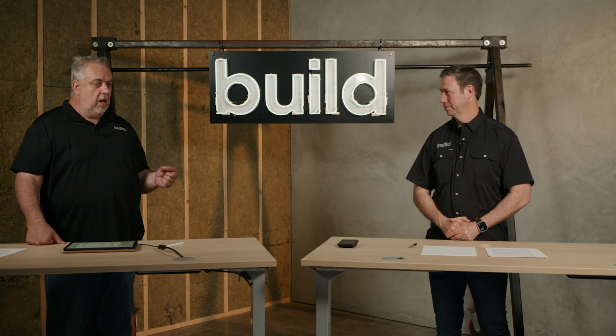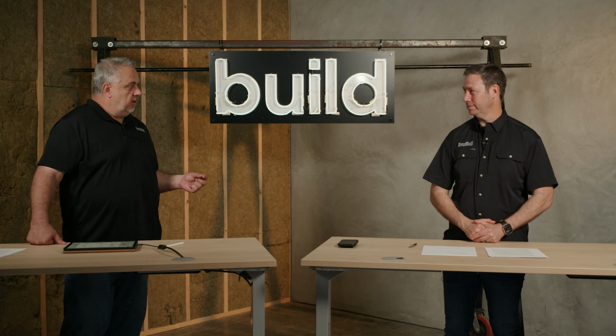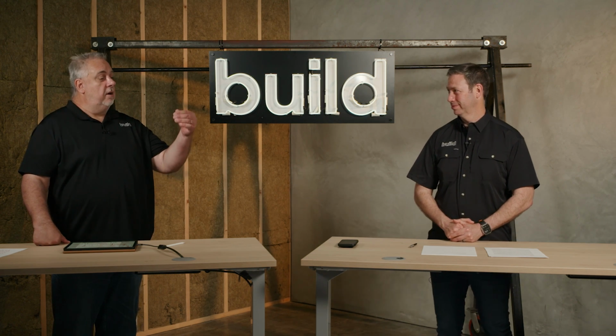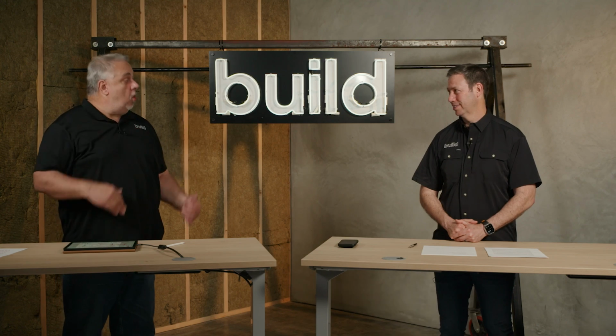When the homeowner called a friend of mine to come and look at the project, the homeowner also gave him a small tidbit of information. We just redid the mason work, right? Because the original build had brick fully mortared to the WRB. The mason came and blamed it on the WRB failing. Oh my God. So they stripped the whole house of masonry, put up the WRB, and then mortared the brick solid again. No. Terrible. And I'm sure he was a great guy, a nice guy, thinking that he knew everything.